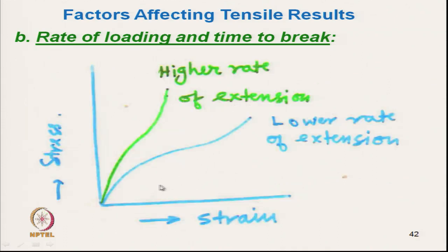Also, we have seen that as we increase the rate of extension, the stress exerted by the material increases. At a high rate of extension, this is the nature of the curve shown by the green line, and at a low rate of extension it is the blue line. Now, based on this basic understanding, we will try to solve a few numericals.